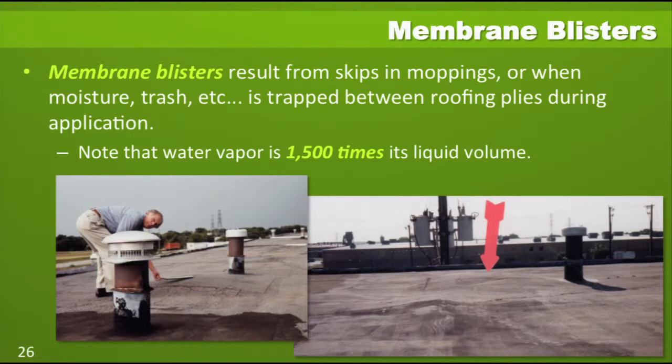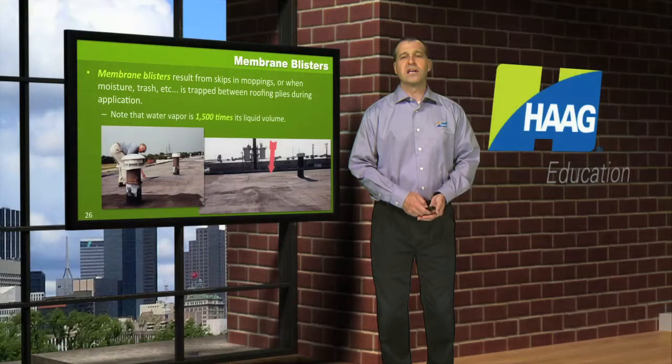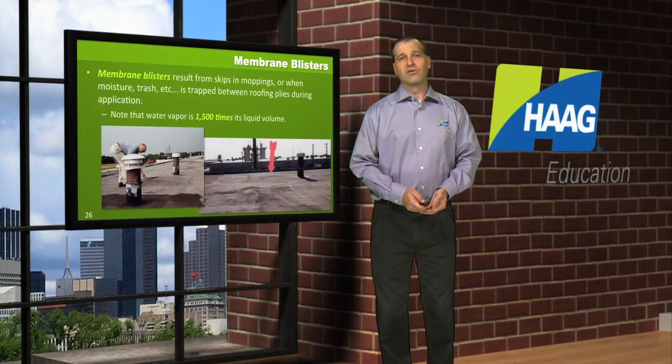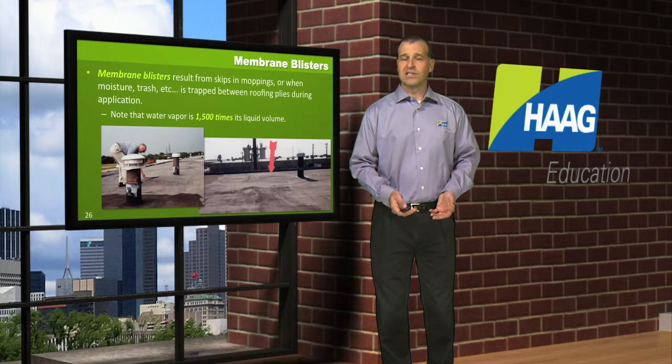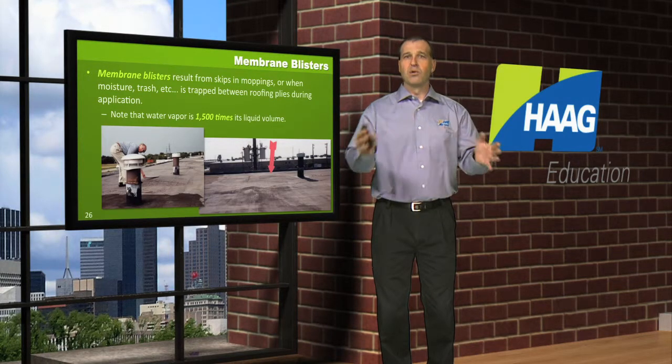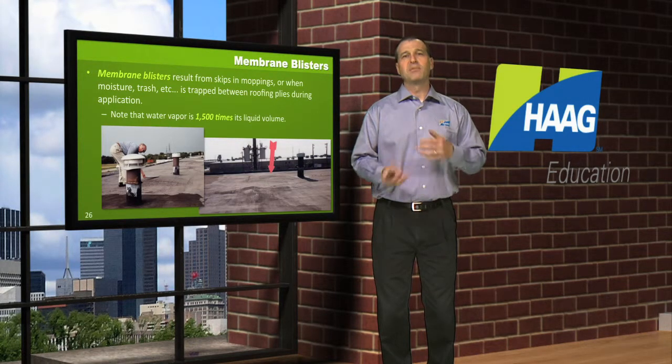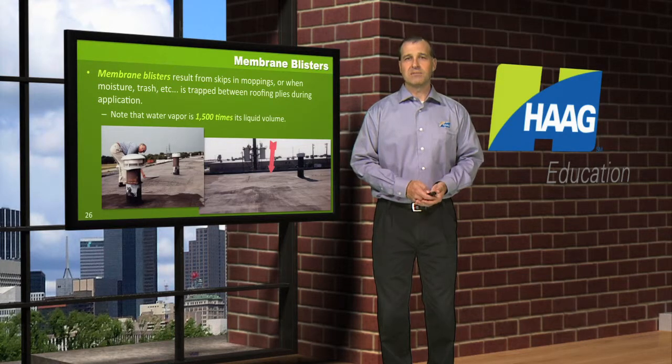in the roof. Another cause for it is if you've got a second roof installed over what was originally a wet leaking roof, then that roof may have moisture in the system, and that may cause these bubbles or blisters to form in between the two roof systems.